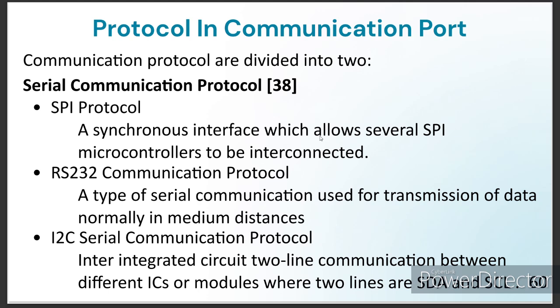SPI protocol. SPI is a common communication protocol that is used by different devices. SD card reader modules, RFID card reader modules, and 2.4 GHz wireless transmitter or receiver, for example, all use SPI to communicate with a microcontroller. One distinct advantage of SPI is the ability to transfer data without interruption.